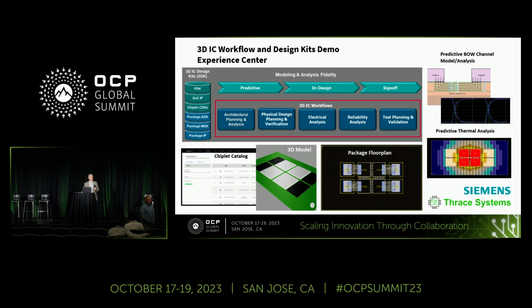How we address it in the CDXML for the chiplet is it rates what ESD it has for that I/O. You know, actually checking ESD in the package is a different problem. That's really more of an EDA problem. Okay, so yeah, I was looking at kind of the die-to-die interface. Yeah, because there are some ESD requirements. Yeah, so whatever ESD level is supported would be defined. There's provisions to define what your coverage is and then the conditions in the CDXML format. Okay, thank you.